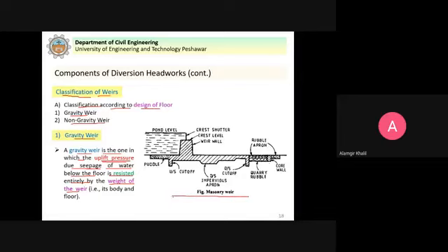Just as an example to help you understand, you see the water level here is high, so here the pressure will be this much. And if we have water level here, it can go from maximum upstream to minimum or zero downstream. It can be zero if we have water level here. So there will be some uplift pressure here.